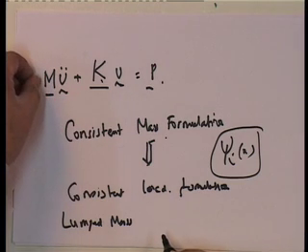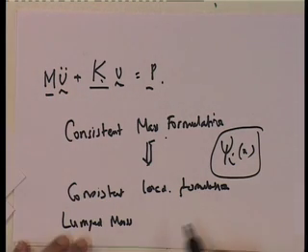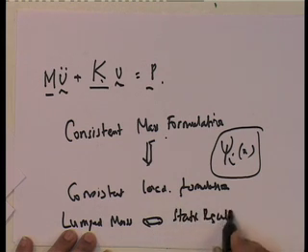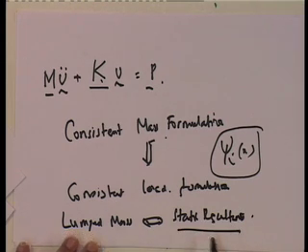see, with lumped mass you get to use static condensation. If you do static condensation, then you should use the static resultants approach, because what happens? In the static resultant approach, we saw that member forces corresponding to rotational degrees of freedom are 0. Okay. So, if you use this, then you can do static condensation, because even at the global level, the P i's corresponding to the rotational degrees of freedom are 0. Okay? So, that in essence is the procedure to develop the property matrices corresponding to any set of degrees of